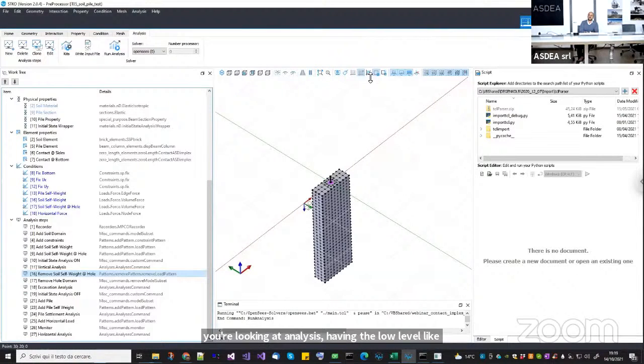Especially for contact. Now, in our case, it will converge, but as I told you, the implex method needs some time steps to avoid those oscillations, okay? So in my opinion, I always prefer to use an incremental volume force rather than the volume force of the element, okay? Actually, in STKO, it's super easy to do it, okay? Because you don't have to worry about writing all the node forces. So if you use STKO, it's much easier to use the volume force command instead of the body forces of the element, okay?